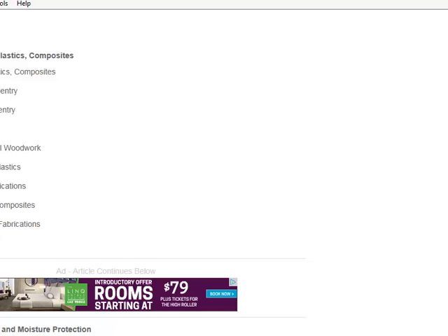Unless you have the stuff that you're sitting at, more like furniture items, that would be Division 12. These things, cubicles, that's Division 12. But any wood casework or plastic laminate casework, wall cabinets, base cabinets, Division 6.